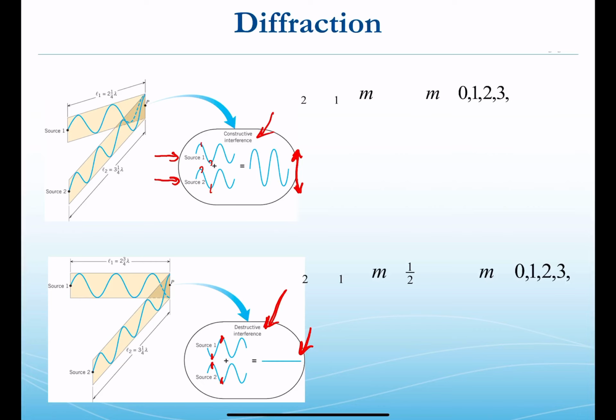This is emphasized in some physics labs. Things like speakers need to be connected correctly to make sure their poles, their positive and negative terminals, are connected correctly. If one speaker is inverted, the sound quality drops remarkably because the sound waves coming from the speakers are in opposite phase, and a lot of the quality of the sound will be canceled.